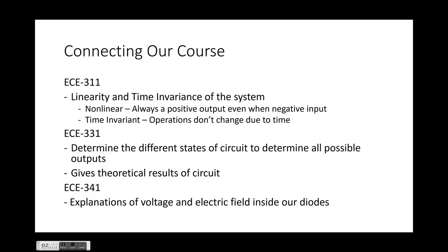So going back through and connecting all of our courses and the importance of everything here, in 311, you can look at the linearity of the circuit and time invariance of the system. Our rectifying circuit is going to be nonlinear because diodes are nonlinear, and therefore our entire system is going to be nonlinear, because we always have a positive output even when we have negative input. And our system is also going to be time invariant because the operation doesn't change over time. It's always going to be the same.